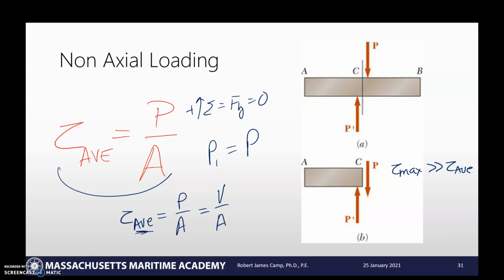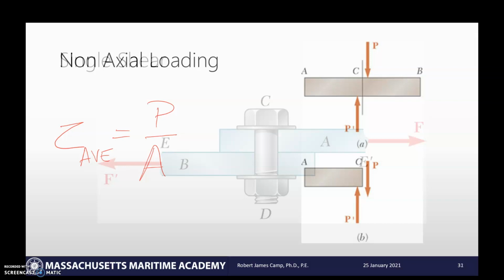So why do I care about shear? Well, we see shear in a lot of common mechanical applications, especially when we're dealing with connectors, bolts, rivets, pins. All of these are going to be a huge factor, because how they fail is completely within shear. Shear force also comes into play when you're using adhesives. Things like super glue and most adhesives are very weak in shear as opposed to axial loads. So we tend to take a look at what's going on there.